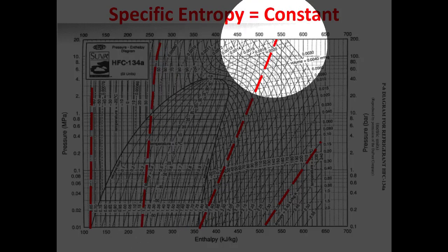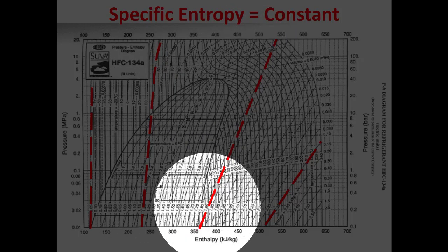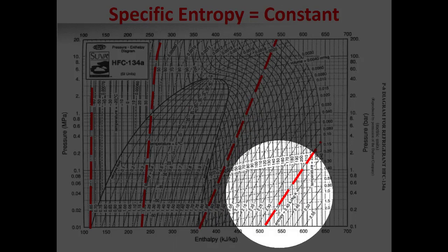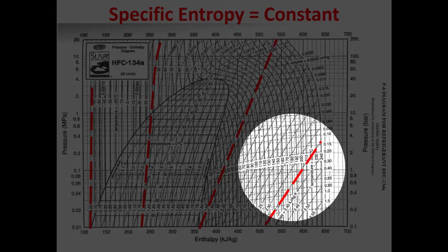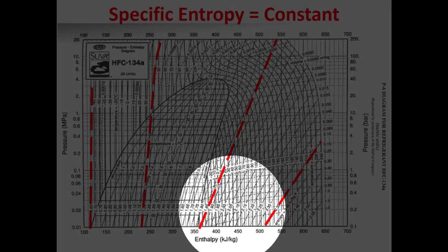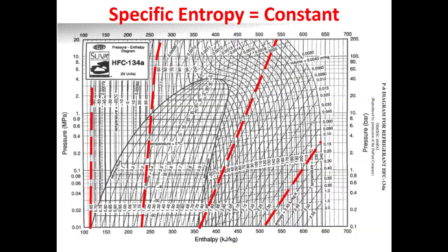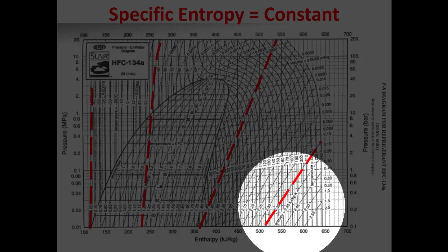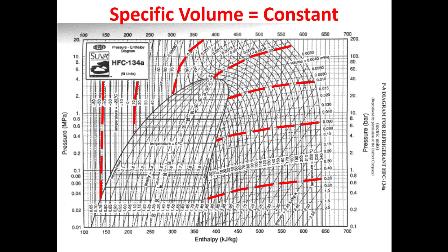And then here, as we're in saturated vapors, the slope keeps changing. So it goes from here to here. There are these constant specific entropy lines that are marked here, so you just have to know where to look on this graph. Over here, it says entropy, but again, what it means is specific entropy. This is in metric units. This says 2.40 kilojoules per kilogram Kelvin.